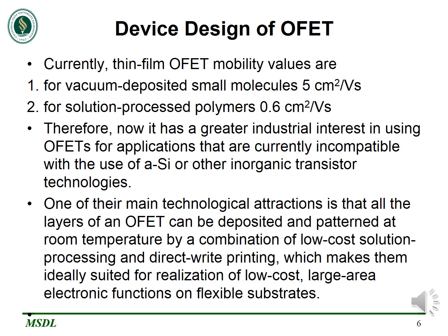One of main advantages is that all layers of an OFET can be deposited and patterned at room temperature by a combination of low-cost solution processing and direct write printing, which makes them ideally suited for realization of low-cost, large area electronic function on flexible substrate.